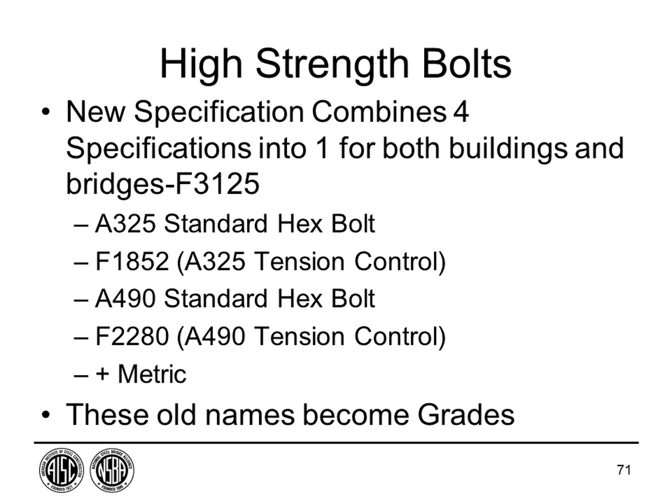Okay, great. And I think we have time for one more question. If part of the web height is in tension and the other part is in compression, does the fracture critical requirement apply to the web portion in tension only? In terms of the weld, it does. But the plate will be ordered to fracture critical. So the butt weld on the tension side will be subject to the welding requirements and the inspection requirements for fracture critical.